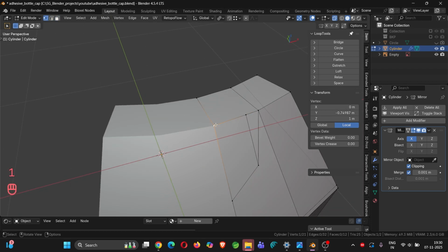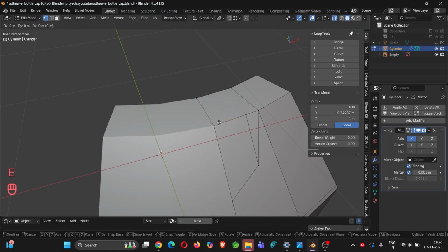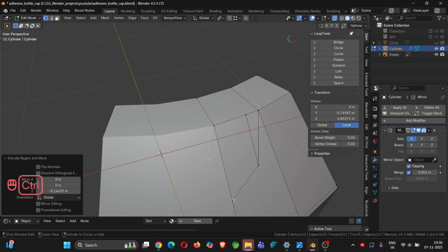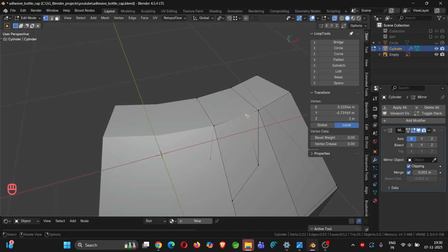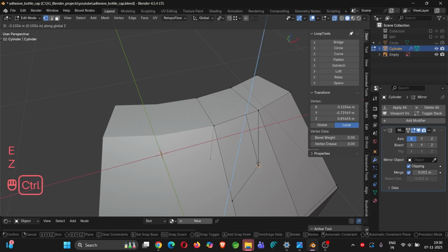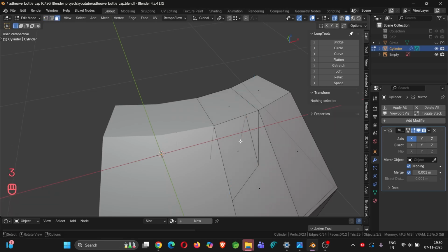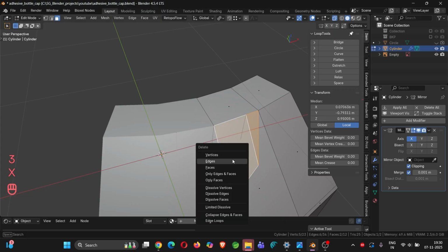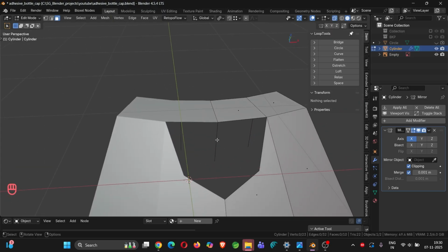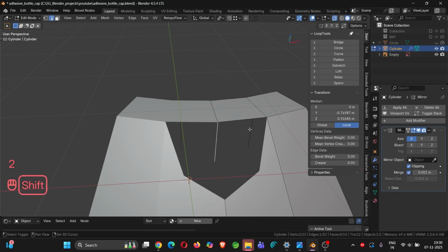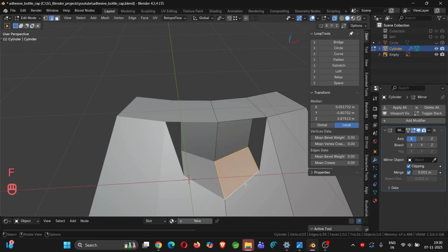Now what I'll do, this vertex, I will extrude along the Z, snap it up to this vertex. So I'll press Ctrl and snap it there. Similarly for this vertex, extrude Z, snap it up to here. Okay. Now I don't need these faces. I just remove them. And if you remember in my screw tutorial, I introduced you to that F2 add-on. That becomes very handy. You just use it to fill the gaps. Okay, and it will take care of all this.